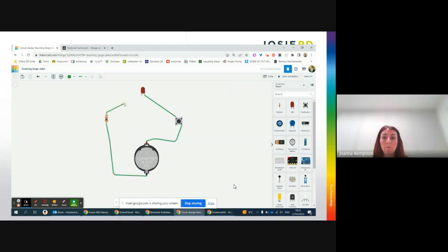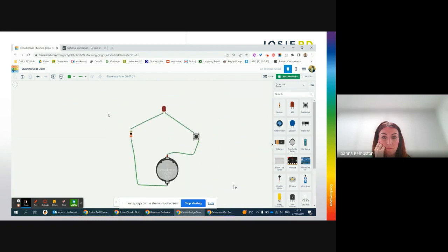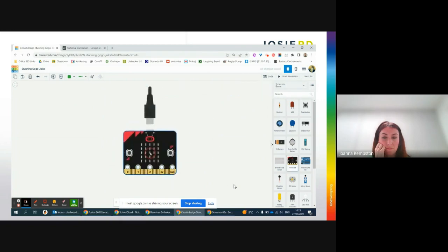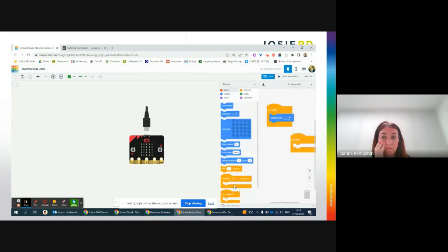see what happens. What's really nice in here is I can simulate my circuit. When I press the button, you can see the LED turns on. And I change the value of the resistor from 1,000 ohms, say 20 ohms. You will see the LED brighter, but I'm also getting a warning message, so the resistance isn't high enough. It's a really nice way to explore circuits and delete all these parts quickly. It's also a really nice way, if you get onto it, for microbits. I can go in here and use microbits and code my microbit in here as well if I want to, and simulate my microbit working as well.